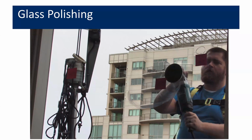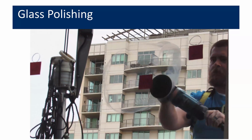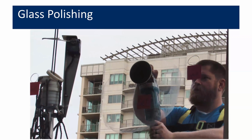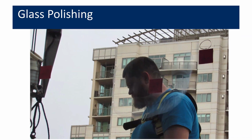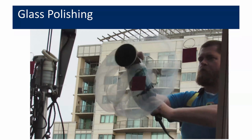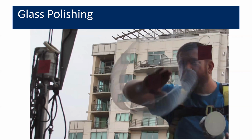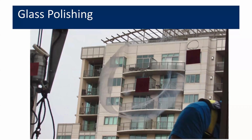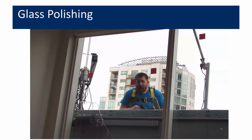And there's several iterations required with this polish because you have to use it in a wet condition. You don't want it to particularly dry on the glass surface because it is a very fine abrasive, but yet it doesn't result in any significant glass blemishes or scratches. So he's going to check whether he got to the bottom of that.